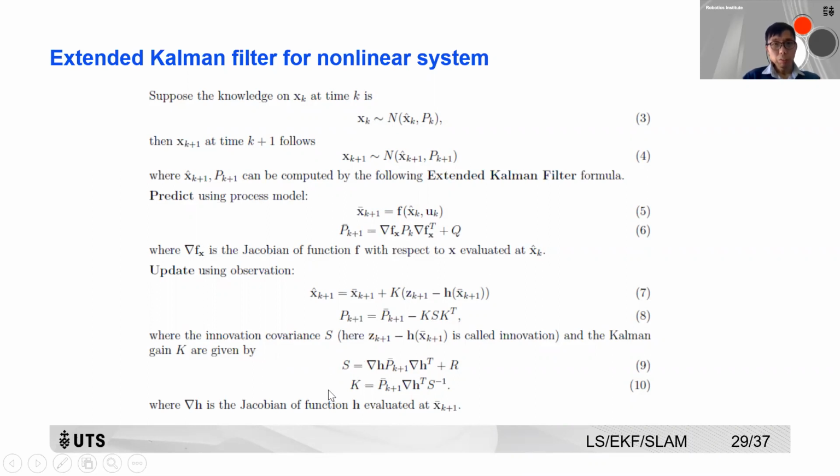And in Kalman filter, we always calculate the innovation covariance, which is S. If your innovation is too large, for example, more than 3 sigma bound of this innovation covariance matrix, then you will say, okay, this is not from this feature.